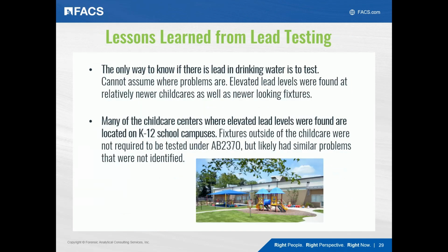Some other takeaways. The only way to know if there is or isn't a problem with lead in drinking water is to perform testing. A lot of times our own assumptions were wrong. We would find elevated lead levels at relatively newer buildings as well as at newer looking fixtures.